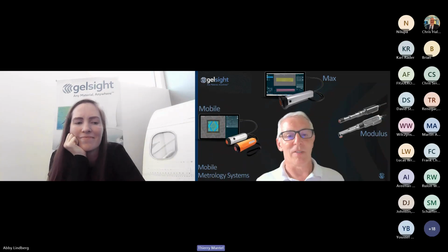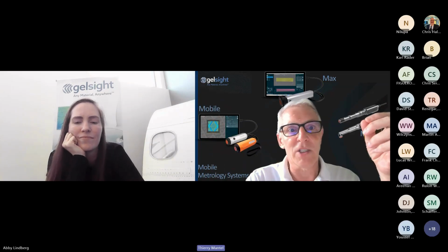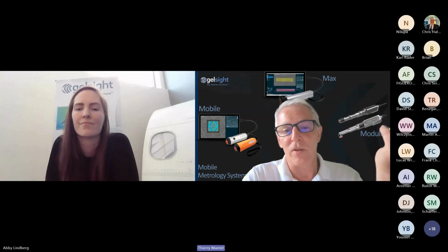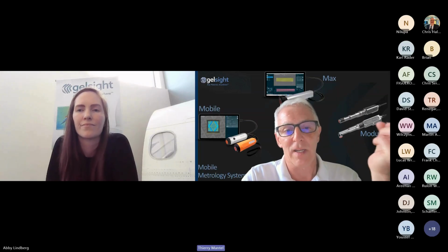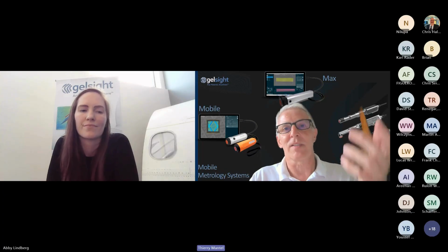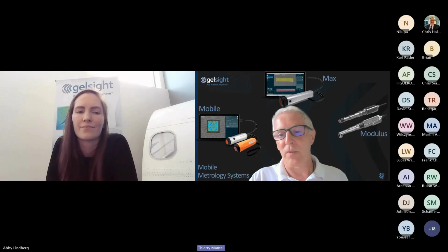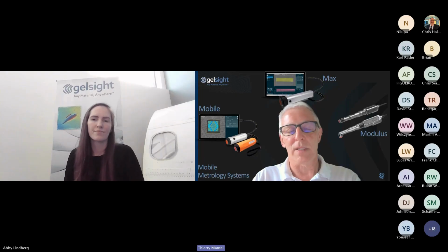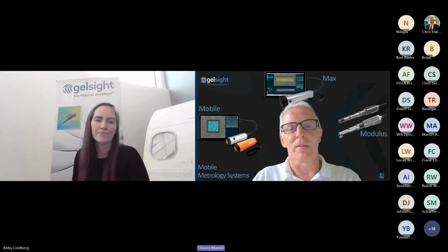You need at least 30 minutes, at least. And with GelSight, you just need 1 or 2 minutes. So there is already a factor of at least 10 to 15 between a classical workflow using putty material and GelSight. When you have dozens of molds to do every day, this really brings very significant value.